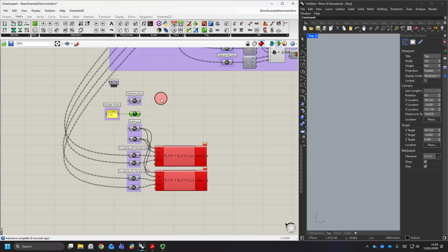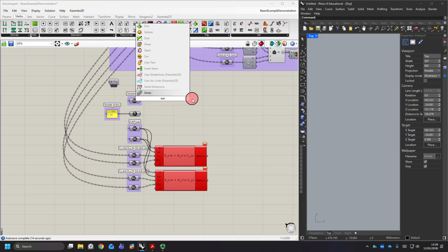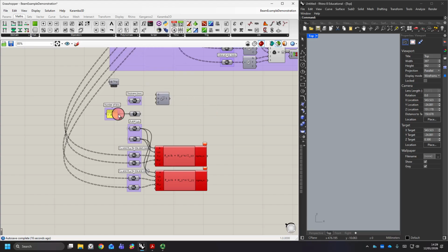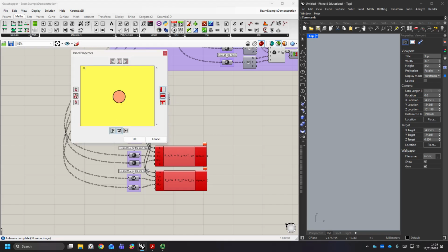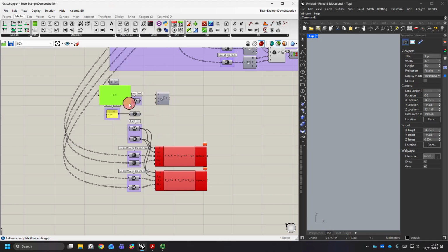And then what I'm going to do, as I mentioned, a little bit similar to before, so I'm going to set up a series, and the start I want to be minus 0.5 times the thickness. So I'll put in just another panel to allow us to do that, and minus 0.5 there. Just to convert that to multi-line data as well. So that will feed in here.